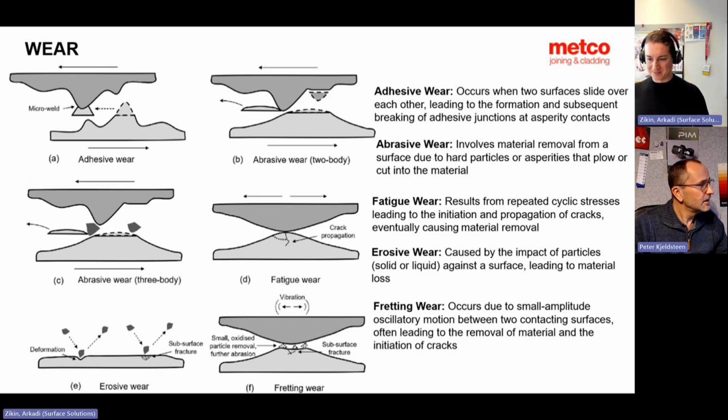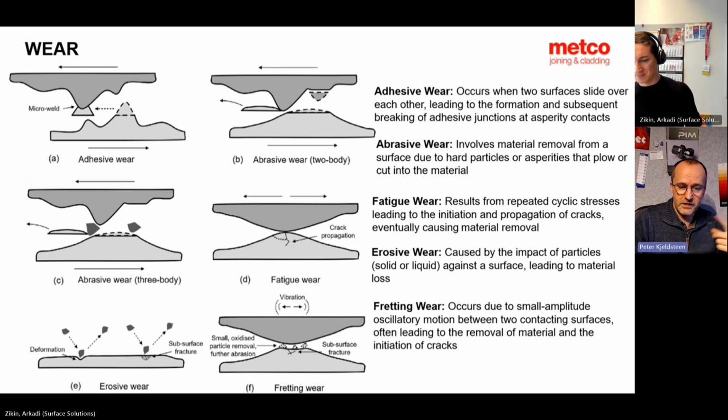No, I remember this fatigue wear in rolling mills. When you roll steel or you roll aluminium or plate sheets, you typically want a roll made of very hard material. But you have this contact point where every time you have a kind of fatigue level, and your highest level of deformation is not on the surface, it's some level below the surface.